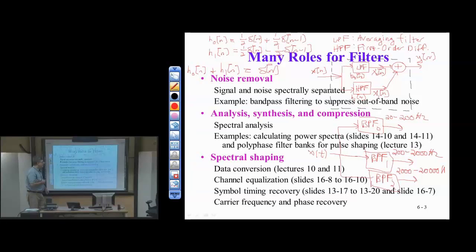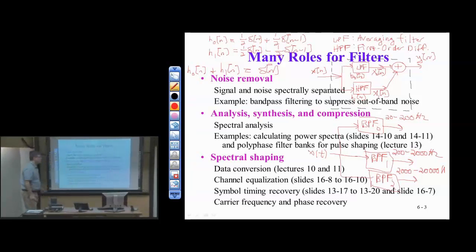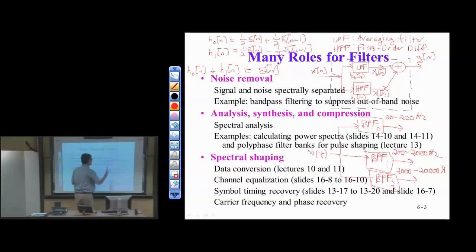That would be great: if we look at the sum of these 3 bandpass filters in terms of frequency response, it gives us a flat or all-pass response over the audible range for normal hearing from 20 hertz to 20 kilohertz. Again, this is an example of analysis. And the previous example was both analysis and synthesis. We had analysis for the bank of the low-pass and high-pass filters in the first example, and the synthesis was simply an addition of the 2 channels. So we'll see this play out in a lot of different ways throughout the class.